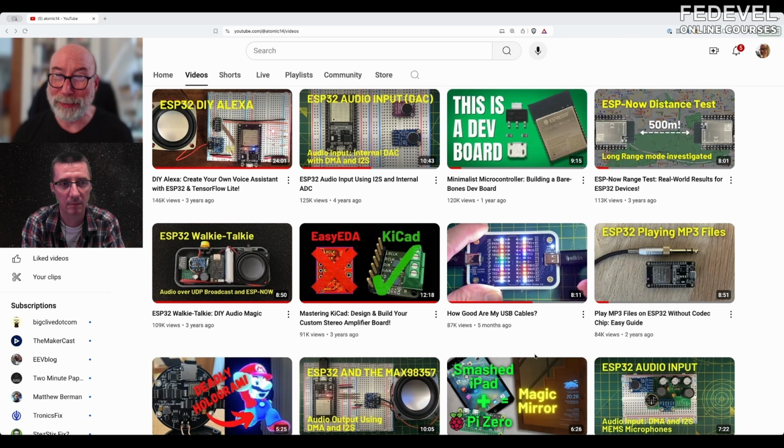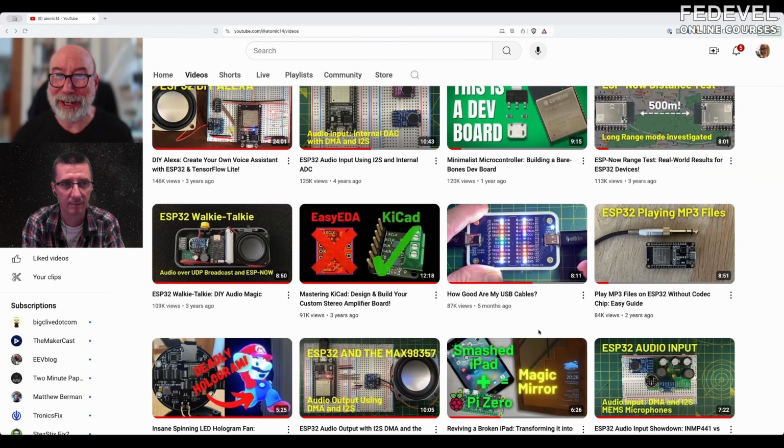And it took me two goes to get something that was actually working because it's really hard with USB sockets that expose every single pin. The pitch is just ridiculous on them, and most of the pins are hidden underneath the socket, so you can't see the connector. It was a complete nightmare actually getting it to work. In the end, I found a USB socket that had exposed pins for half of them and then normal through holes for the other pins. Yeah, because I just could not solder it at all.